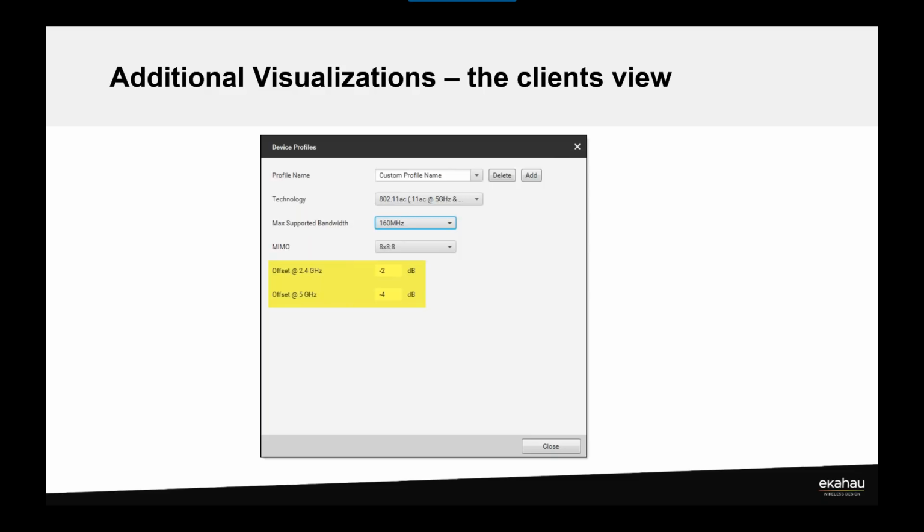That may even involve putting an AP up at no transmit power and looking in the device and seeing what you're receiving there, to know what the offset is. So you may have to figure that out yourself if it's not documented somewhere easy to find, or actually look at the chipset manufacturer's documentation more so than the documentation that's shipped with the device, because that's a value that most users will never understand or never need to know. So it's not something that is prominent on specification sheets usually. You may have to go to the actual chipset vendor to find that out.